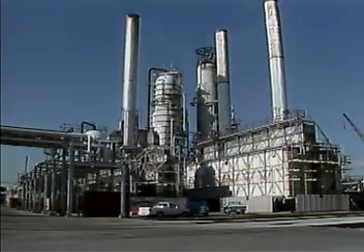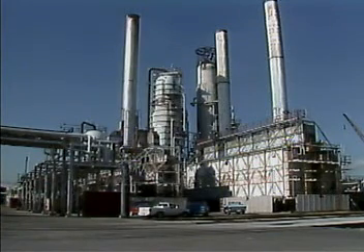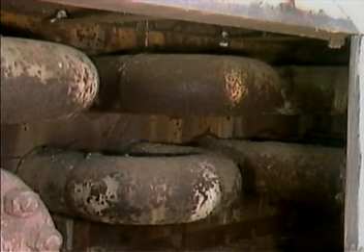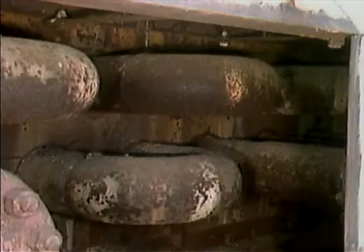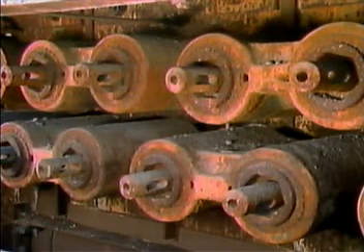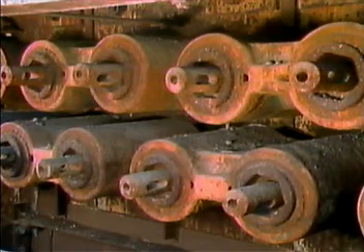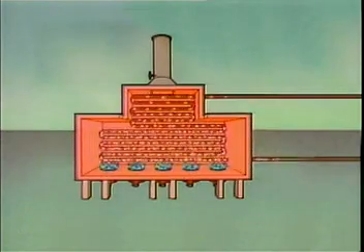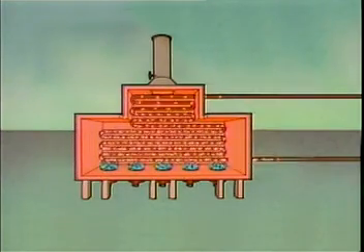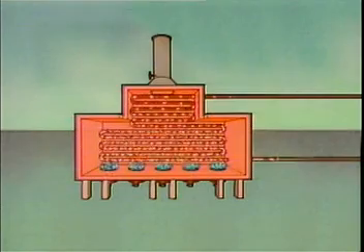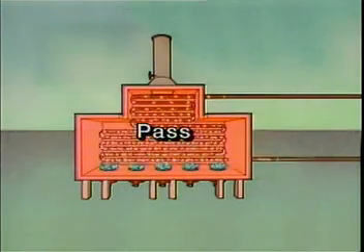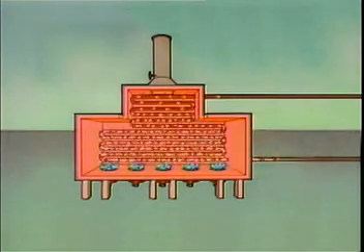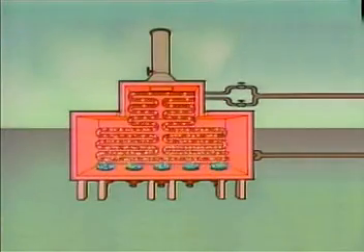Regardless of the design of the furnace, the tube arrangement has to allow for a continuous flow of process fluid. For example, these tube ends are connected with tubing bends. In other tube arrangements, the tubes are connected together by enlarged sections of pipes called headers instead of tubing bends. The route that the process fluid takes as it flows through a furnace depends on the design of the furnace. Each continuous, uninterrupted path that the fluid takes is called a pass. This furnace is a single-pass furnace, but many furnaces are multi-pass types.